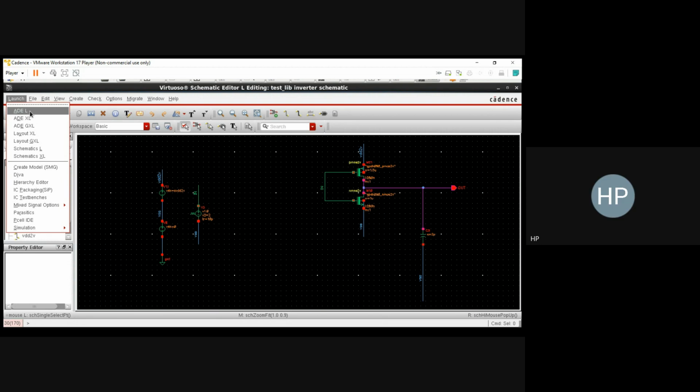Yeah, for a long channel MOSFET, the mobility of NMOS will be twice the mobility of PMOS. If we decrease the technology node, suppose we are working on 5 nanometer, then for both we will keep the same length. When we do the characterization for the inverter, we will see whether the output and the input are crossing at the midpoint. We find the W by L ratio of PMOS to the W by L of NMOS for which the output and input cross at 0.5 of VDD.